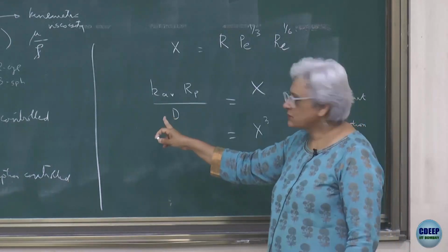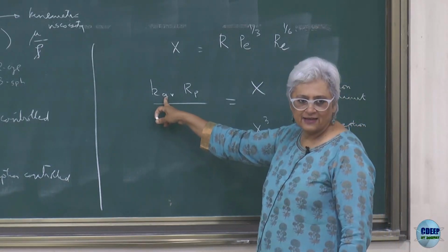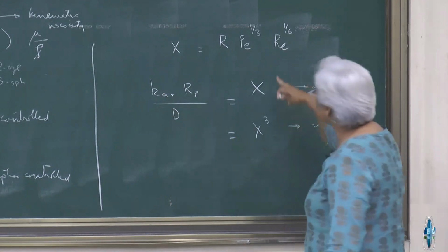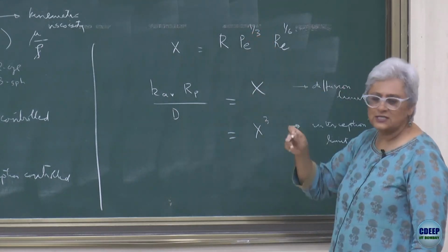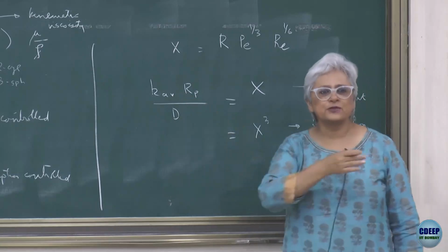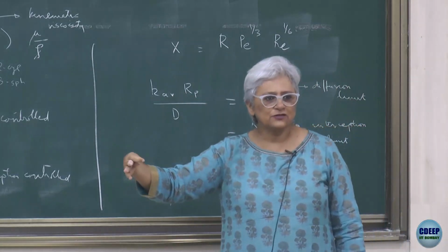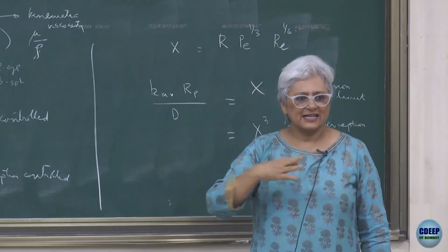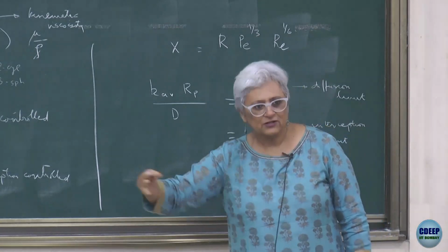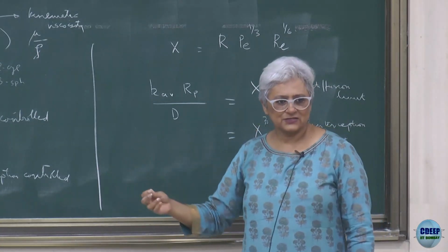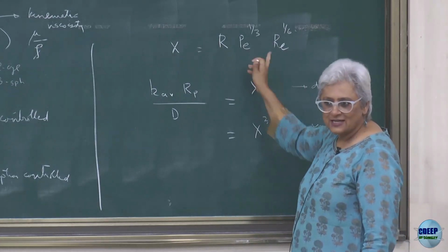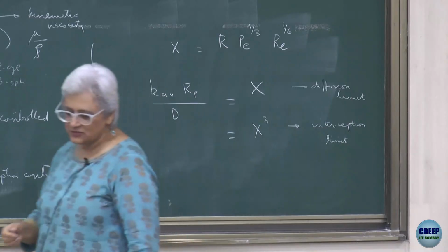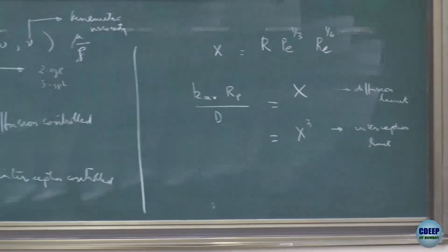Right? And so we can get a, and this is now in terms of a Peclet to the 1/3, etc., etc. And what had we done with this Kavg? We said, okay, let's now think of it as a single fiber, and let's go ahead and do the flow analogy and the mass transfer analogy, and that's how we had got a Peclet to the -2/3, right? So you go ahead and do the same sort of thing, and what we end up with